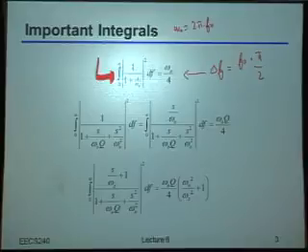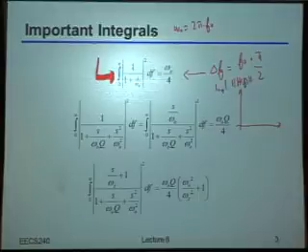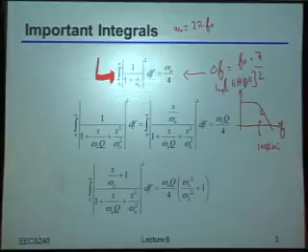So by the way, I'll remind you, or maybe I'll ask you guys, what is the shape of a first-order low-pass filter to begin with in the frequency domain? Yeah, okay, so everybody made the right hand motions, right? So if we plot h of f, and I'll do it in the log domain just because I'm lazy to draw it the right way, versus f, you see something that looks like this, right? Where, as I'm sure you all remember, this roll-off here is 20 dB per decade. Okay? So procedurally, when I'm doing this integral, what is it that I'm doing? How would you draw that on this curve here?